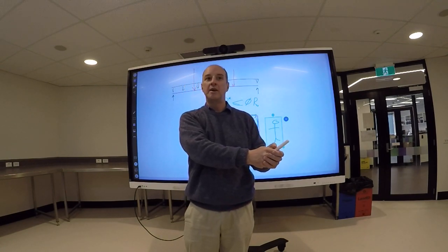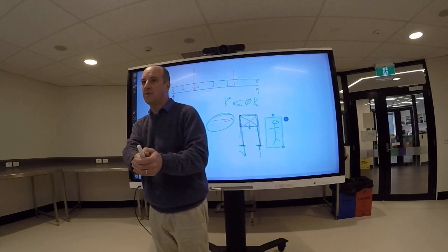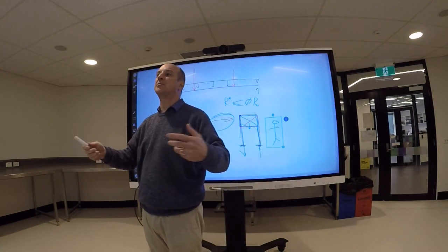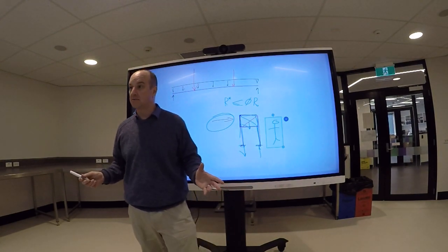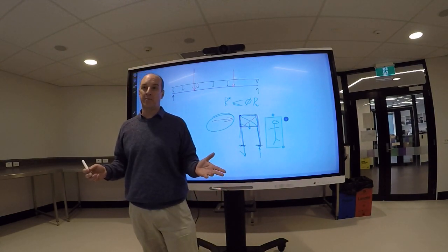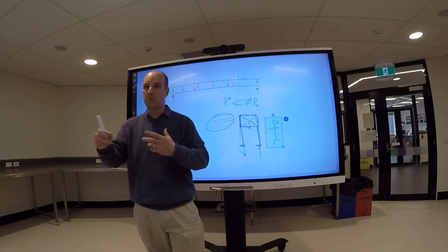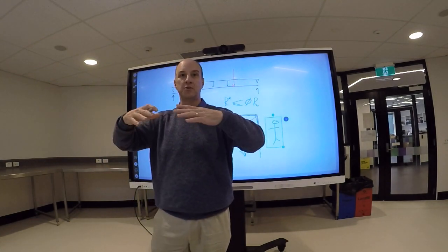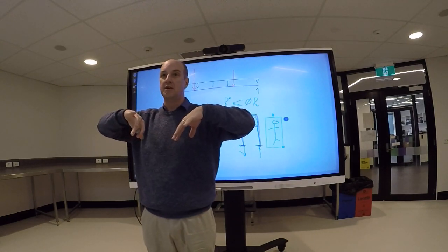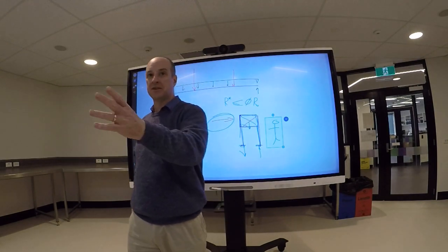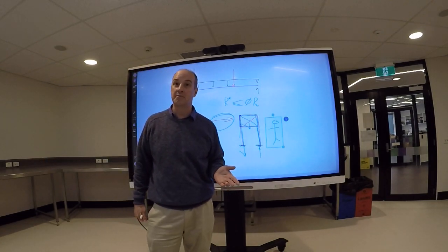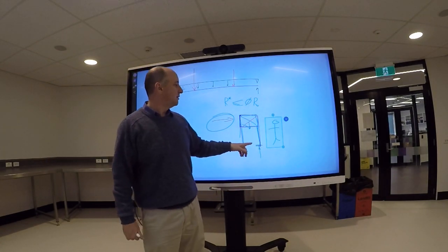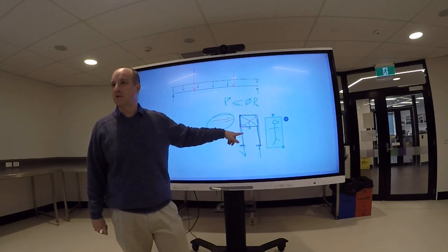All right? In fact, if you're designing an underground car park, it's a really good idea to make sure that any particular column could be removed and the thing is going to stay there. Not to say it won't be damaged, like you still have to prop it up, repair it. Maybe it's going to make the floor sag and all the stuff's going to fall off the shelves. And that is a serviceability failure, that's okay, but it's not a safety failure, it's not going to bring the whole building down. All right. Equally, with a sign like this, you say, yes, an airplane could crash into it.